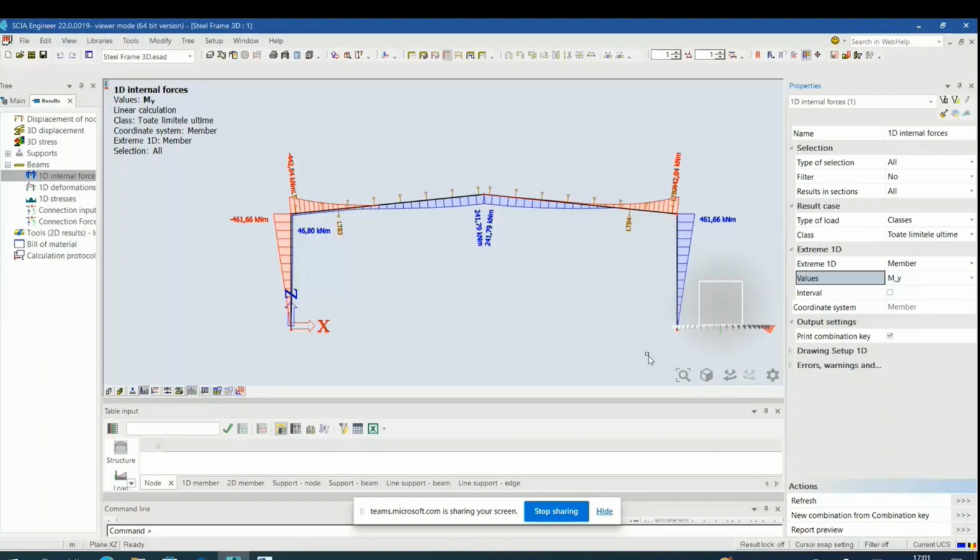Depending on the panel, you have to return to your design model and run again, to check again. For this reason, it's better to have a uniform load, and the distance between the purlins is not important. When you have more than 4 concentrated forces on the beam, you can usually take it like a uniform load.